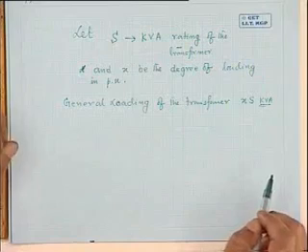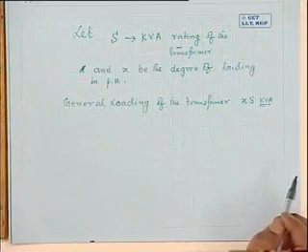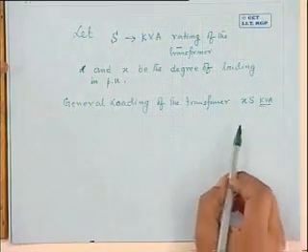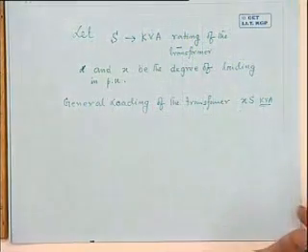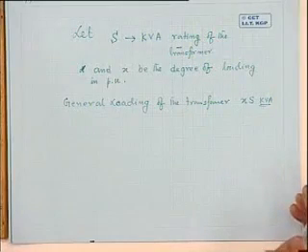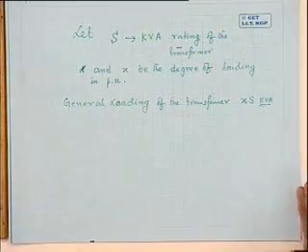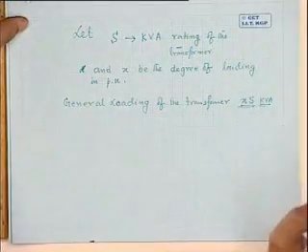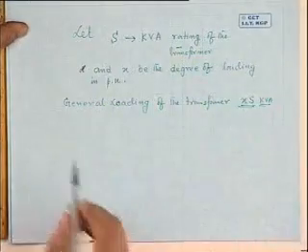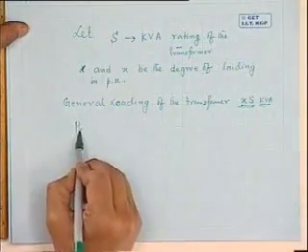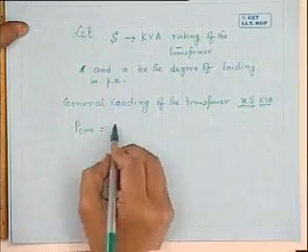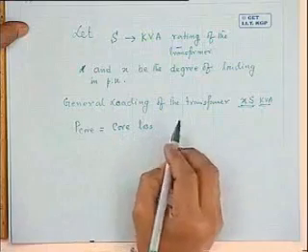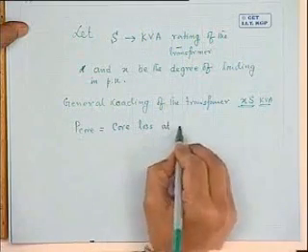I mean, a very simple concept. Where should X vary between? 0 to 1 normally. You can slightly overload it. If it is greater than 1, the transformer is overloaded. So X simply means that, nothing else. That is half loaded, three-quarters loaded, like that. So this is there. Let us also say that P core be the core loss of the transformer,